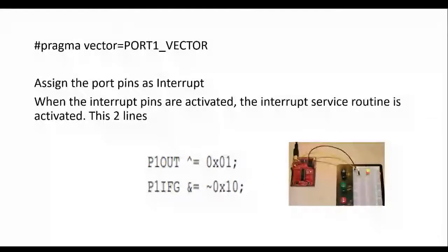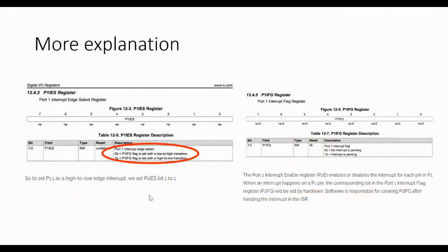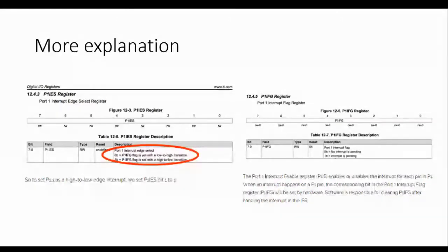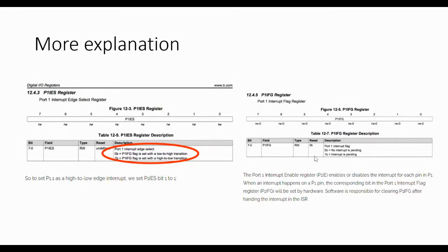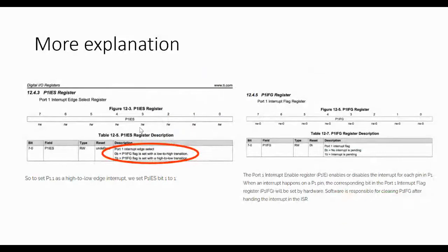So when you have a transition, meaning the user presses the button, the interrupt service routine will run, and the flag will automatically turn on. Now, is this flag important? What if I don't configure this flag at all? Will the code still work? My answer is yes. This last line is basically optional. Without it, the code will still blink the LED.